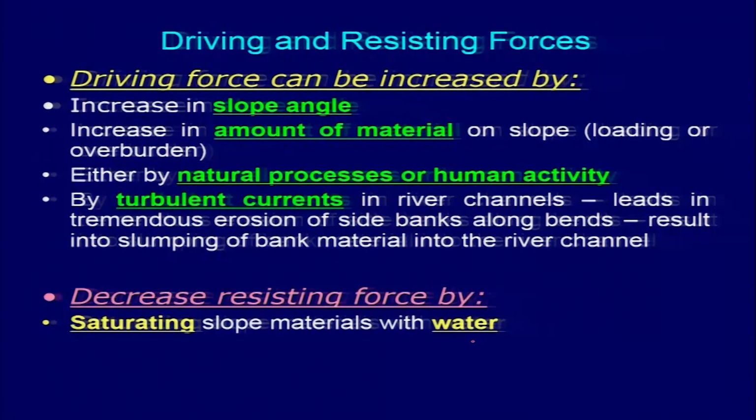They try to construct small waterways or canals so that it can be drained out as early as possible. And if you allow the water to percolate down, then the material may get oversaturated, which will result in a decrease in resisting forces.